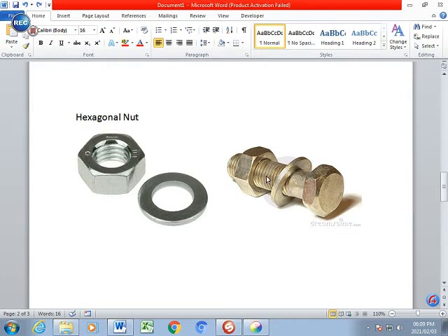That is the threaded portion there, that's the non-threaded portion, and these two are always accompanied by each other. So you put in a washer first and you insert a nut after the washer, so that the nut does not make immediate contact with the component which you are basically tightening.